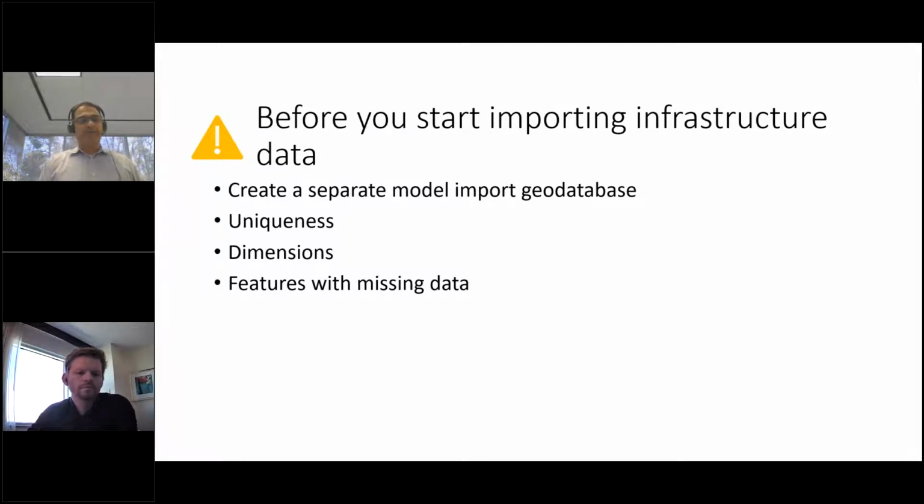This way, we're not delaying the development of the model, but we acknowledge that there are facilities that are incomplete in terms of data. Now, if it's in the middle of the system, you want to do something different, like interpolation, or actually go and survey that, because you're creating a gap in the middle of your system. But if it's terminal, nothing flows into it, you can deactivate it and move on until you have the rest of the data.